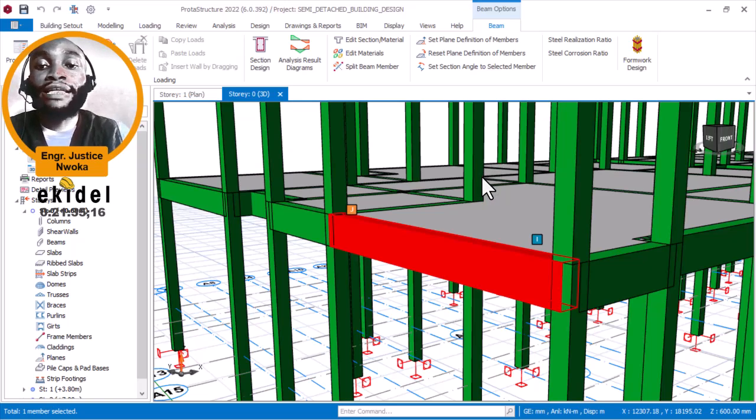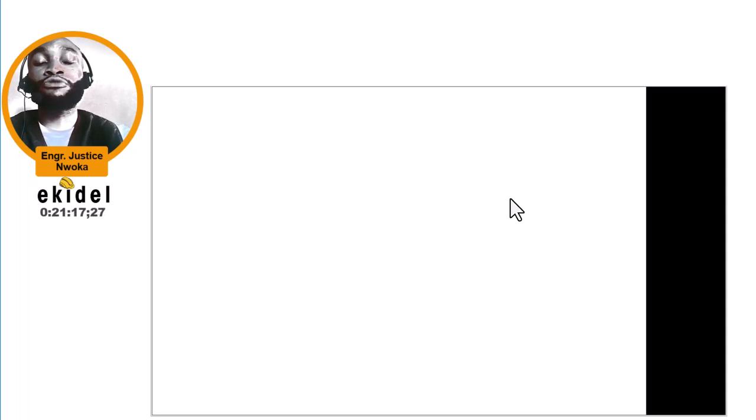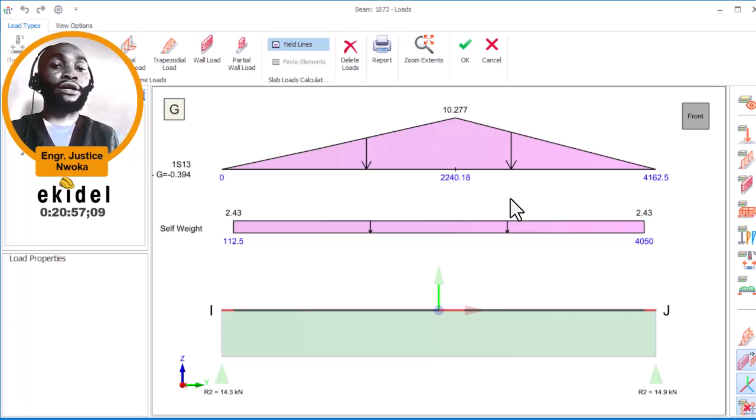On editing the story, it now displays a different interface. I will also show you how to calculate your wall unit weight based on your height. Many people feel that the 3.47 we give here is the actual one, or 2.98. No, it is affected by the height of your story. If someone has a story height of 4 meters, he will have a different load.